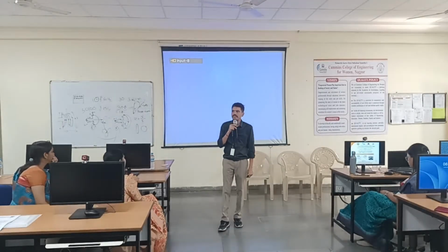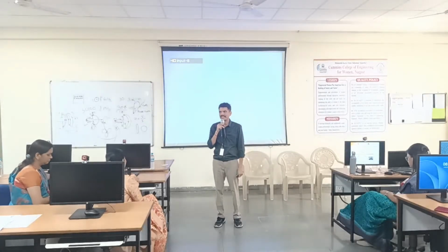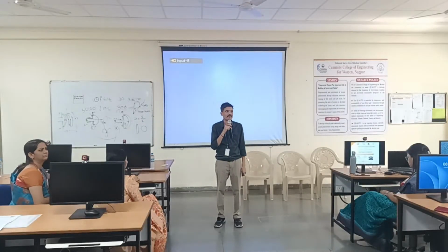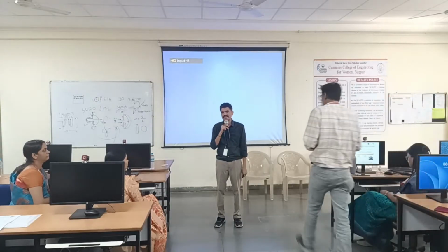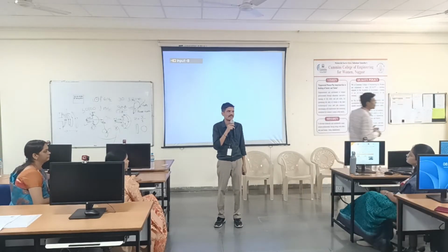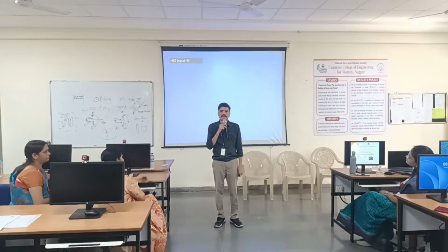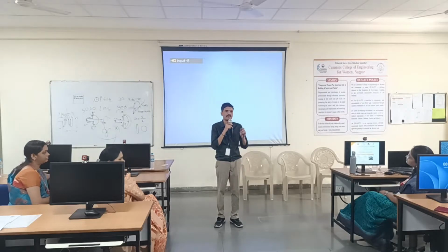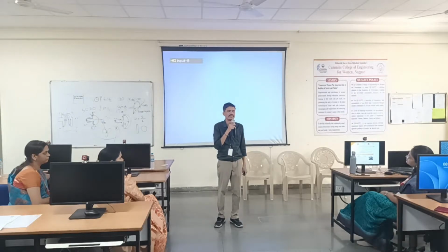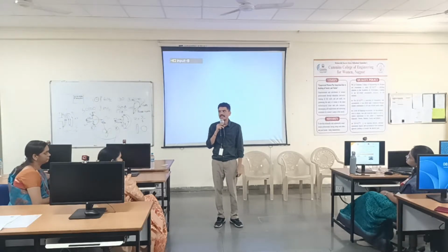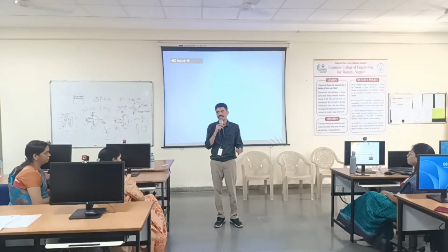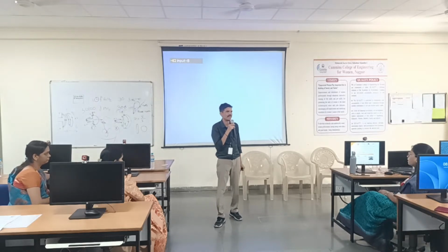The purposes of these two amplifiers are different. Though both look like amplifiers, what they actually do with your electrical signal is completely different. When it comes to the low noise amplifier, the LNA should amplify the signal to optimum strength, with the condition that it should produce minimum additional noise during operation. That is the job of the LNA.